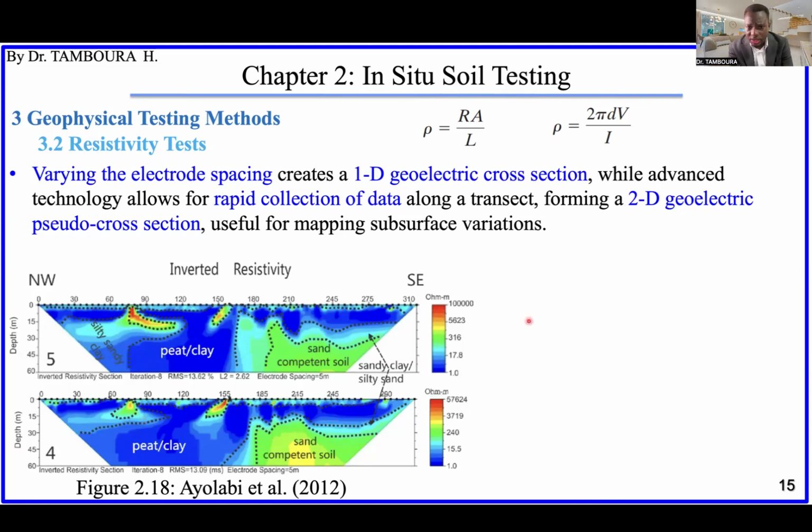And you can see here, it is measured in ohm meters. Ohm, because R is resistance, electrical resistance, which is measured in ohm, right? And resistivity involves area divided by length. Square meter divided by meter will be meter, right? So that's why you have here ohm meter.